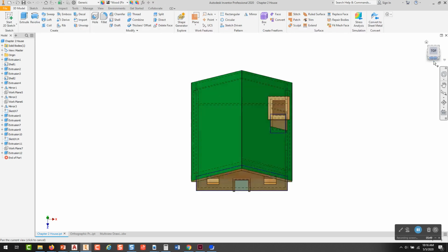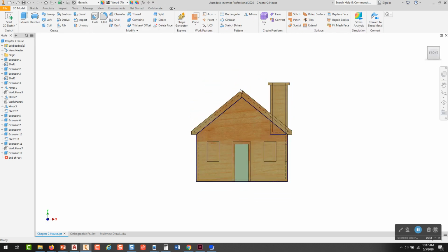Now I'm going to come back to this view. So that's the edge of the inclined plane, and this is the edge of the inclined plane over here. The surface that's highlighted right now, our line of sight is perpendicular to this surface. And when we're perpendicular to a surface, we use a term called normal to the view. So we are normal to the view of this plane here. We are normal to these eaves right here.